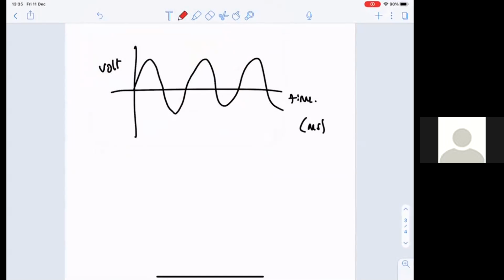If you took the average of every point of the graph, it'll run through the middle of it, which is 0. Because every time there's a point up here, it's counterbalanced by a point down here. So they cancel each other out, which is why we do the root mean square. So Catherine's explanation of it was perfect.